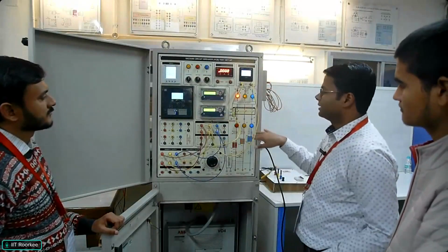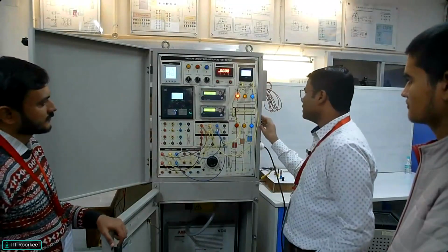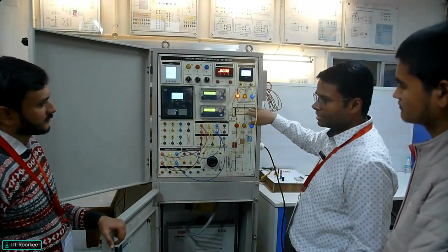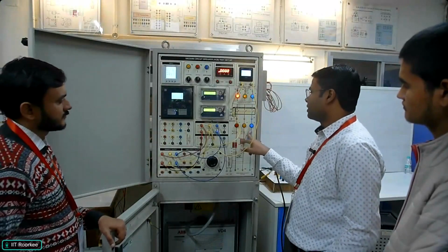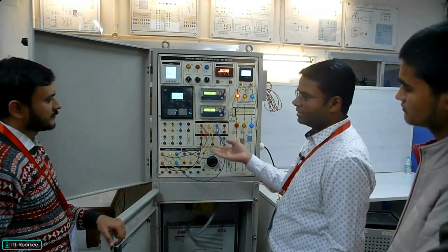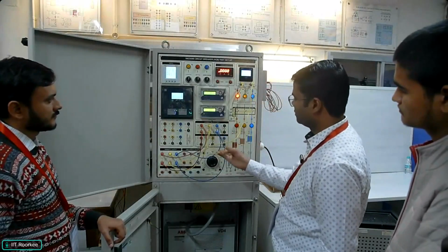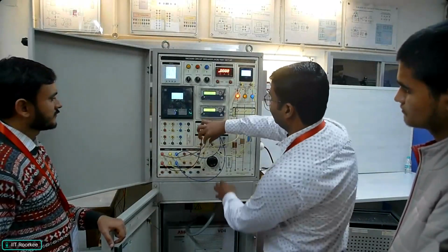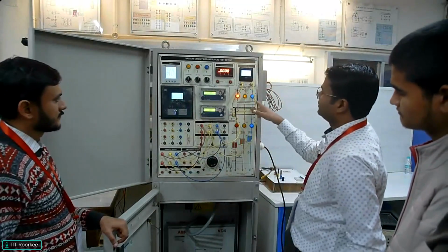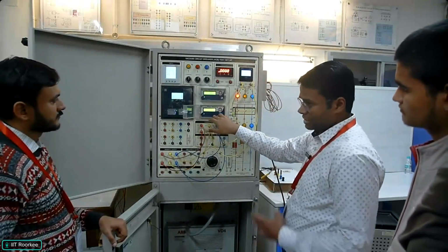So if you see, a three-phase AC supply we are giving to that side, and after that you will see our circuit breaker is connected with that. Here the relay is connected. The relay primary is connected with the line and the secondary will be connected to the relay as usual. We have connected an ammeter in B phase, in series with that line. So we will see the current here, and we can also see it on the display of the relay.